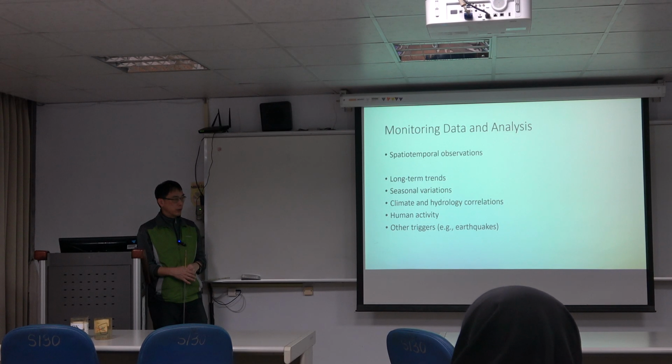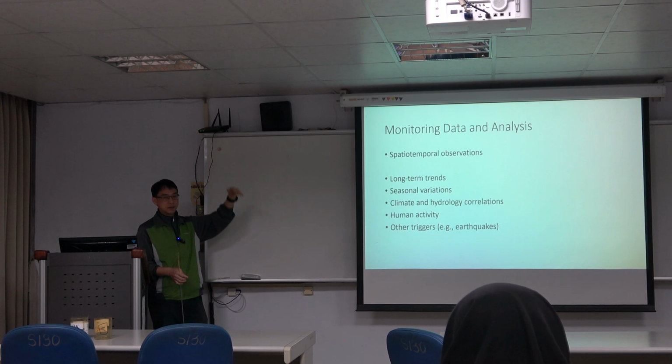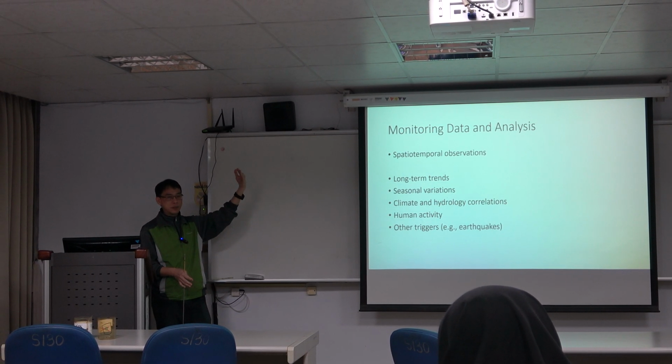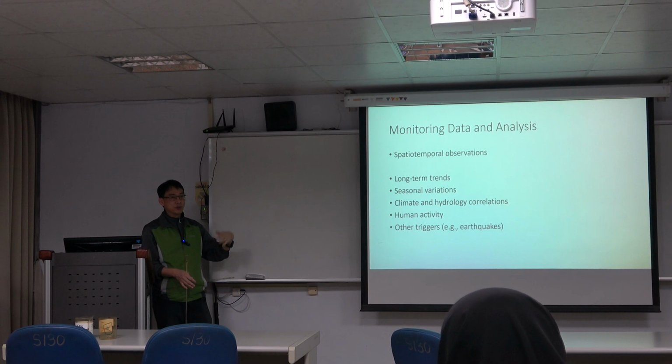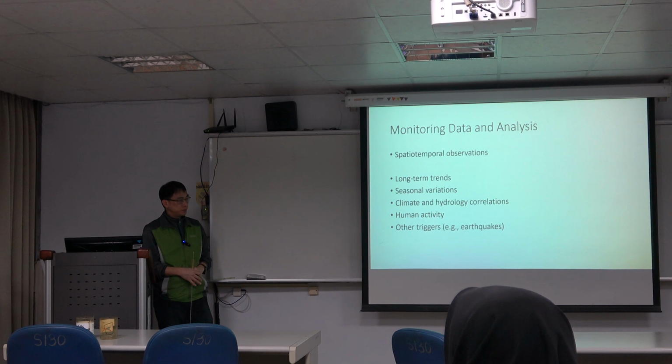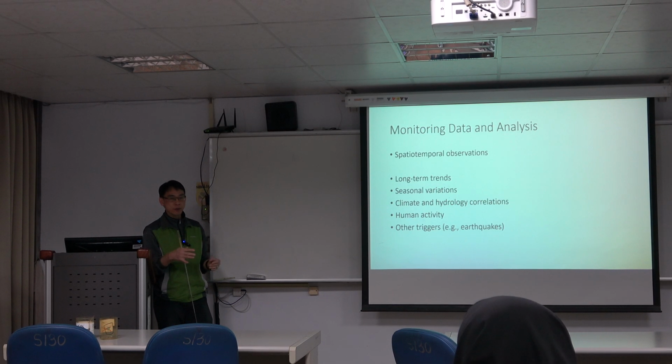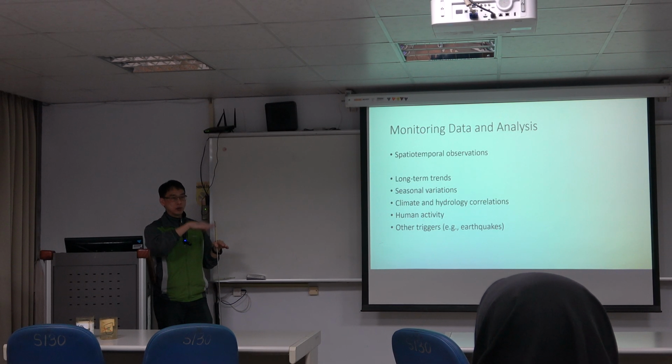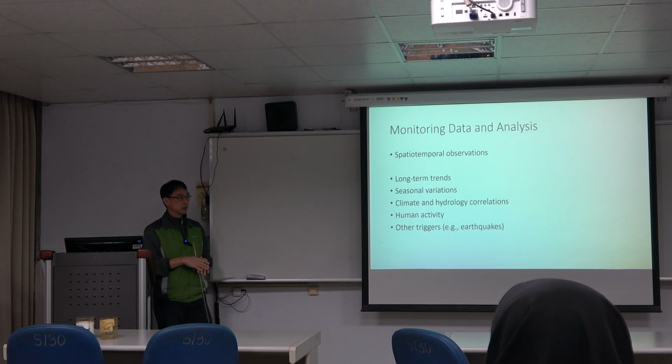Like when a typhoon is coming, there are low barometric pressure conditions, and your groundwater level will uplift largely. That could be over 10 centimeters, so that might affect some of the behaviors, but not very seriously. And if your wells are close to the sea in the coastal area, tidal variations also affect your groundwater system. So you are able to have some variations and influences. That could be an interesting part.